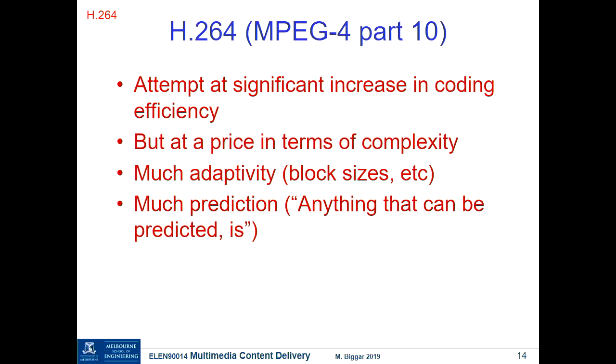These days, we're trying to get away from it. The latest systems, 4K for instance, very high resolution video, are not interlaced. But given that we have all this material that is interlaced, and we still have TV cameras that are doing interlacing, we have to encode the output as best we can. And so, recognising that there are those artifacts that occur within a frame if we put those two fields together, we come up with these different coding approaches.